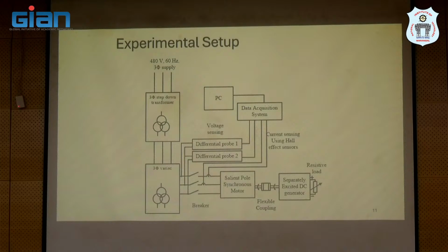So a data acquisition system in which you can sample at a high enough rate to capture some of the lower order harmonics of your currents and voltages would be quite helpful. Especially if you recollect the MMF permeance analysis, we found that there are sideband frequencies. If you have 50 hertz, you get 75 hertz and 25 hertz. The 75 hertz is greater than 50 hertz, so that should be used as your frequency of interest if you are trying to capture it. So you may have to capture based on those kinds of higher frequencies.